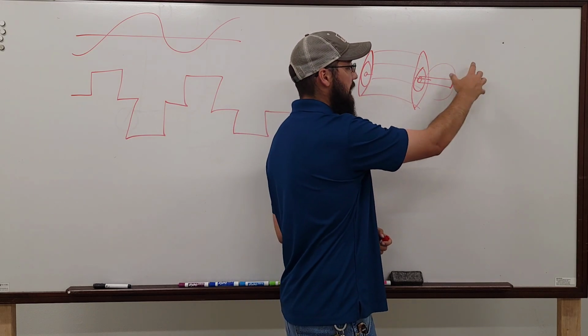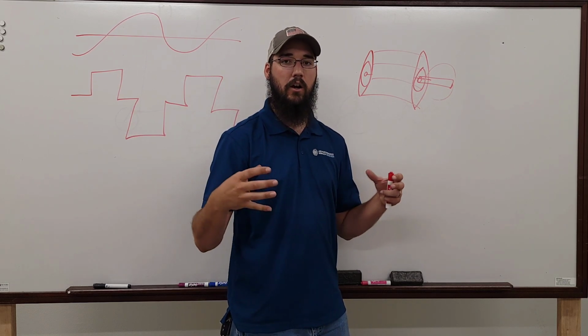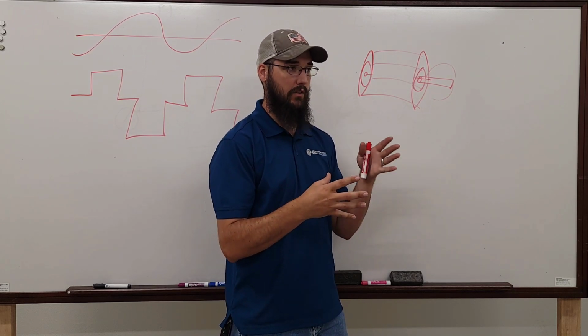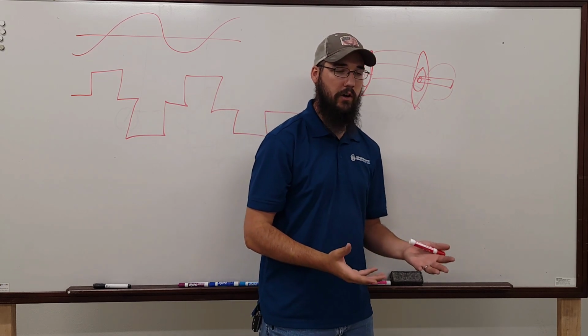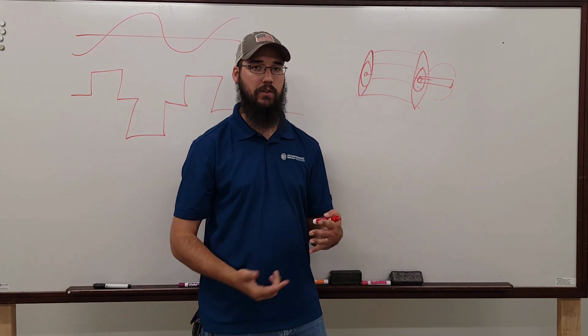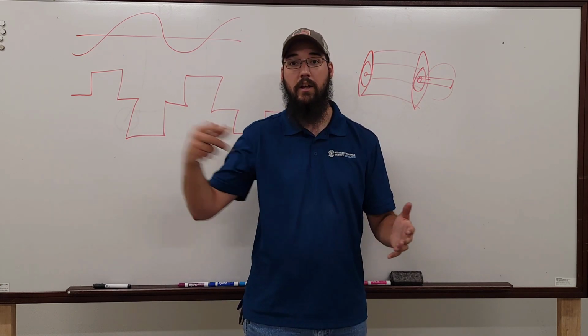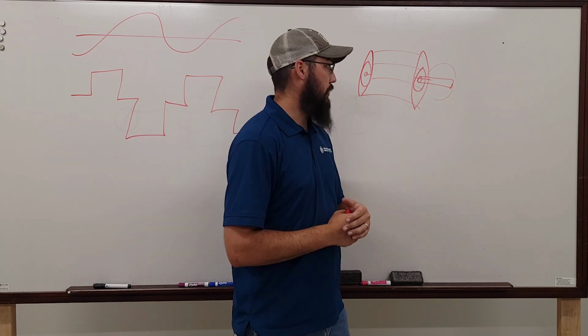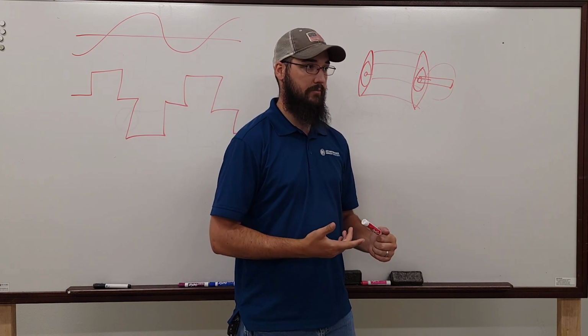So what happens is, because this is usually isolated, right? There's a rubber coupling on a pump that separates the motor shaft from the pump shaft. On a majority of our air handlers, we've got belts on the system. Well, obviously the belt is an insulator. It's not conducting anything across it. There's only one place for that charge to go, and it's right through the bearing.